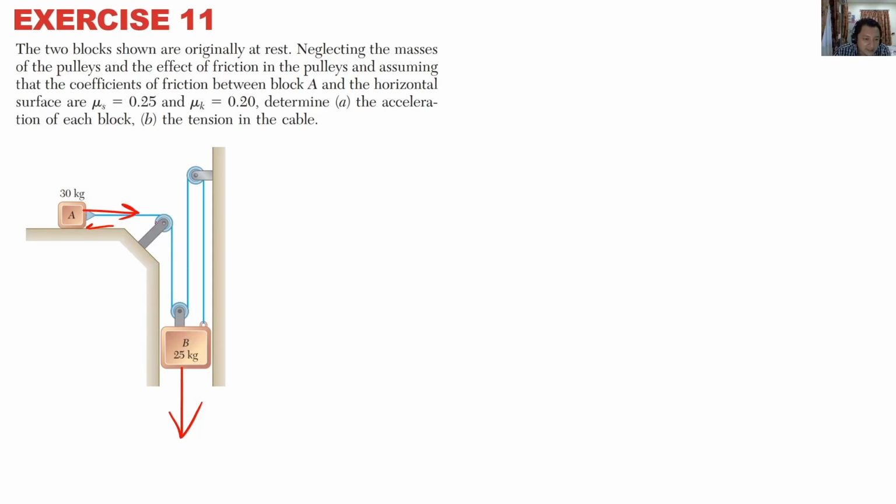And you have something called, again, dependent motion. Due to everything is connected using one single cable. So 2 blocks. So remember, you have to cut your cables and apply equilibrium, and wherever you cut, you're going to get tension, tension, tension, right, at the location of your cuts, at these 3 locations. Okay, so let's read properly.